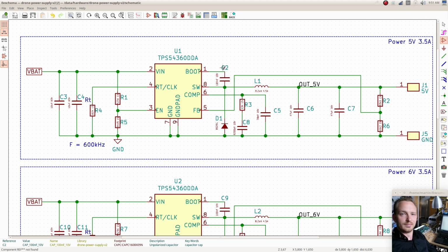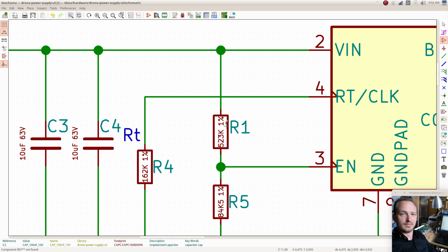Anyway, what I usually end up doing is specializing all of the default templates that KiCad provides, and creating components that are specific for my schematic. And for this resistor, for example, I've added the value of the resistor as text in the component, which ensures that I cannot change this value, and this value should never be changed.